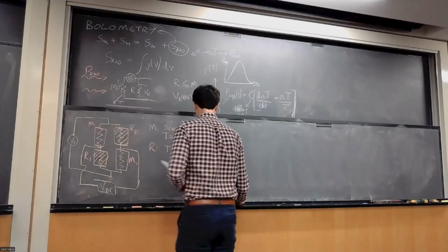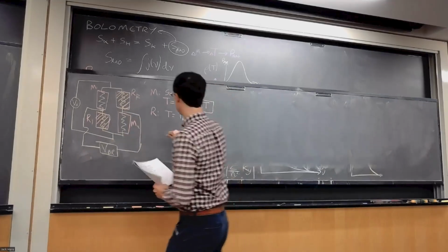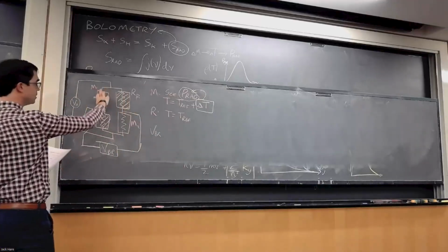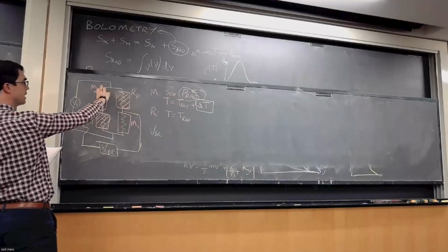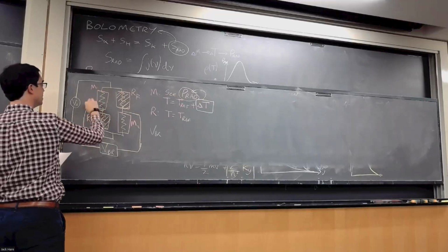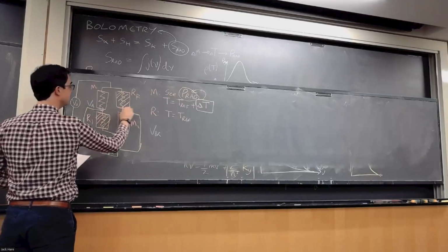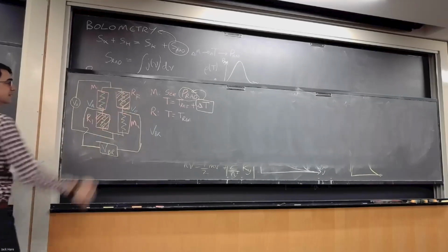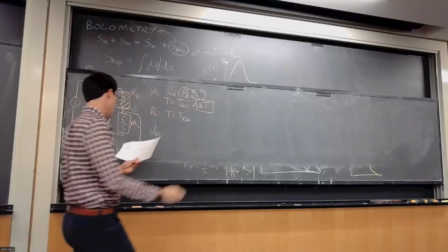And we do this because, or the way that we do this, is we notice that V bridge is the difference between 2 potential dividers. One potential divider that goes on M1, R1, and so the potential that this floats at here, VA, is going to be different in general from the potential that this floats at, VB, where the 2 resistors are arranged in the opposite way round.